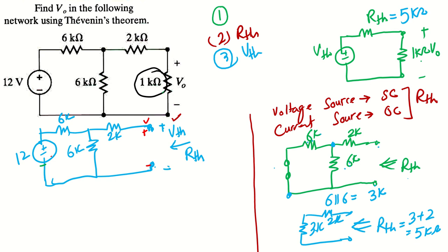If the circuit is complex, you can use source transformation, nodal, or mesh analysis. Our target is to find the voltage drop here. But this circuit is very simple. We know that we have an open circuit branch here, so no current will be flowing through this 2 kilo ohm. So the voltage drop across 2 kilo ohm will be 0.